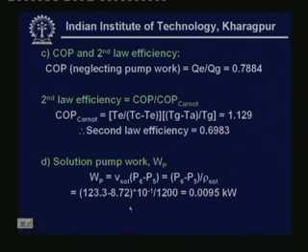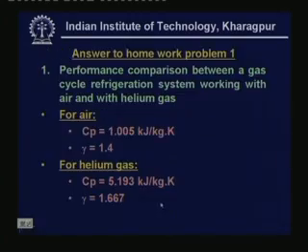So, this is the typical problem on absorption systems. Okay. The procedure is almost the same as compression systems, but absorption system is a little more complicated, because you have to deal with the solutions and you have to find the properties of the refrigerant as well as the solutions. Okay. For that you need PTX and HTX data. Once you have the data and once you identify the state points properly, you can easily calculate the required performance parameters. Okay. So, these are two typical problems. Now, let me give the answers to homework problems.